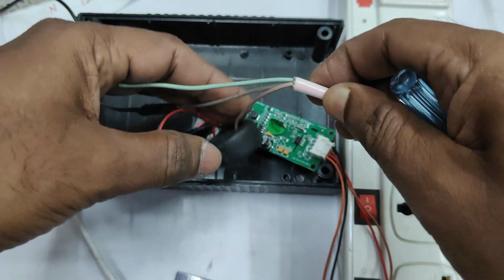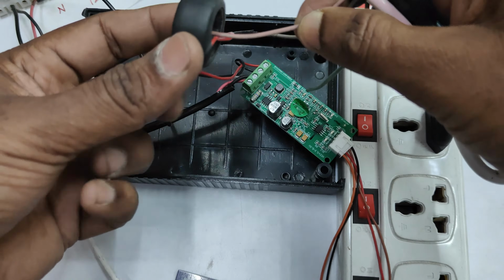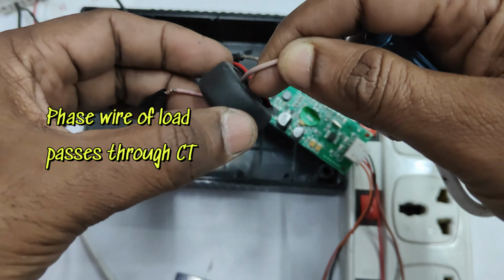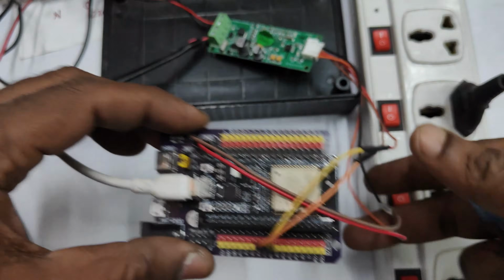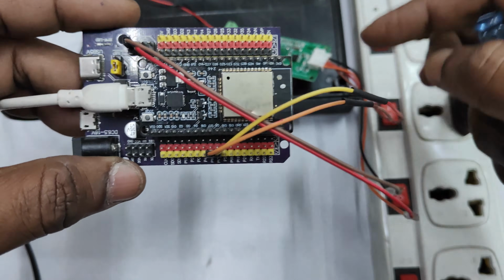For the load we are using a power strip. The 3 pin top is cut, and we have taken the phase wire through the CT coil, and the phase wire reaches the 230 volt phase through this CT coil. The neutral wire directly reaches the neutral.